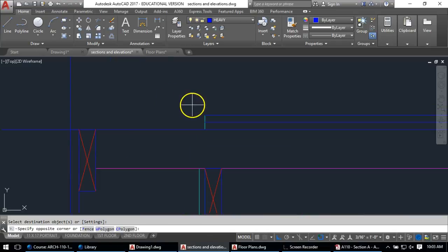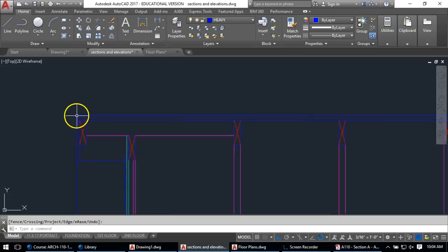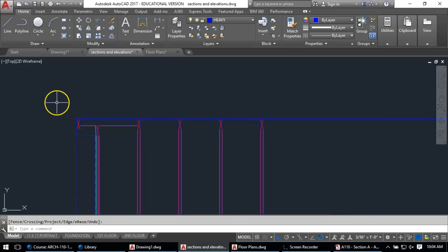Actually, this line doesn't need to go there. The roofing material of course goes completely over everything there. And there's a metal drip edge there, which you can see, looks like there's a little line in the blow-up. The reality is, if you want to show that drip edge, you need to draw a bigger section than I think we're working with here. So we can put the note in, but I'm not going to do any particular drawing in this case to show it. But that's the edge of the roof going all the way across.